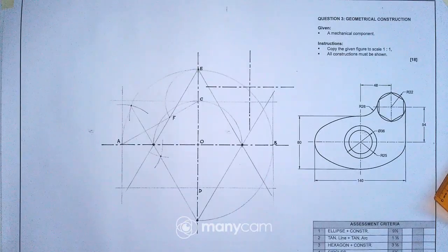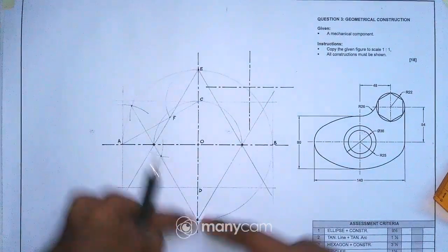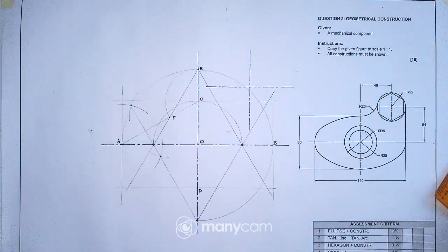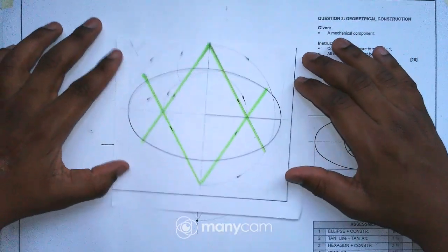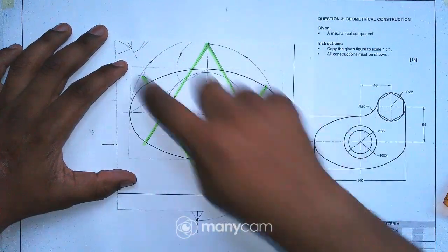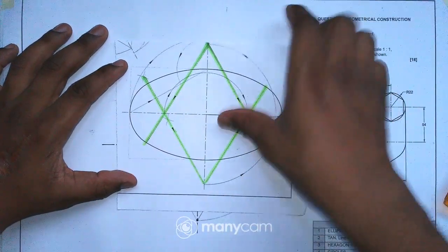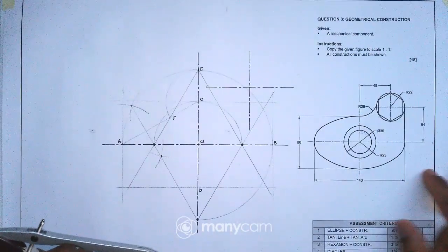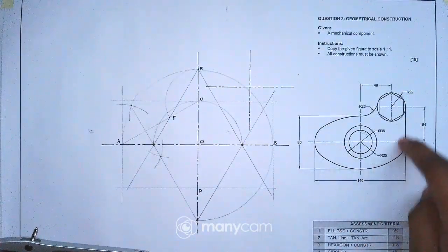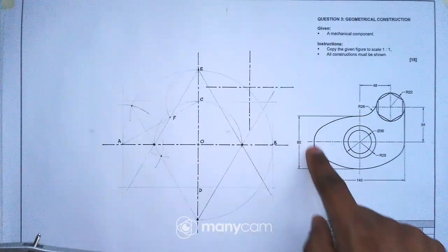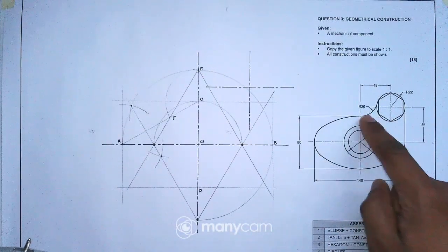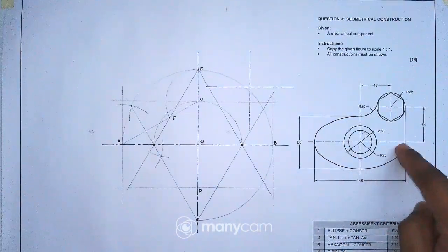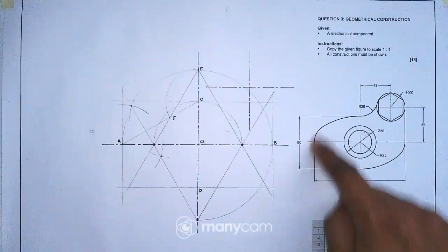So now, because I have the V facing down and the V facing up, it means that I can now draw that ellipse. Earlier I showed you this and said we must have these lines for us to draw the ellipse. So now I'll go ahead and draw the ellipse, but bear in mind this is not a full ellipse. As you can see, it's almost a full ellipse, but we don't have an arc there. So I can draw this section in using outlines, solid lines.